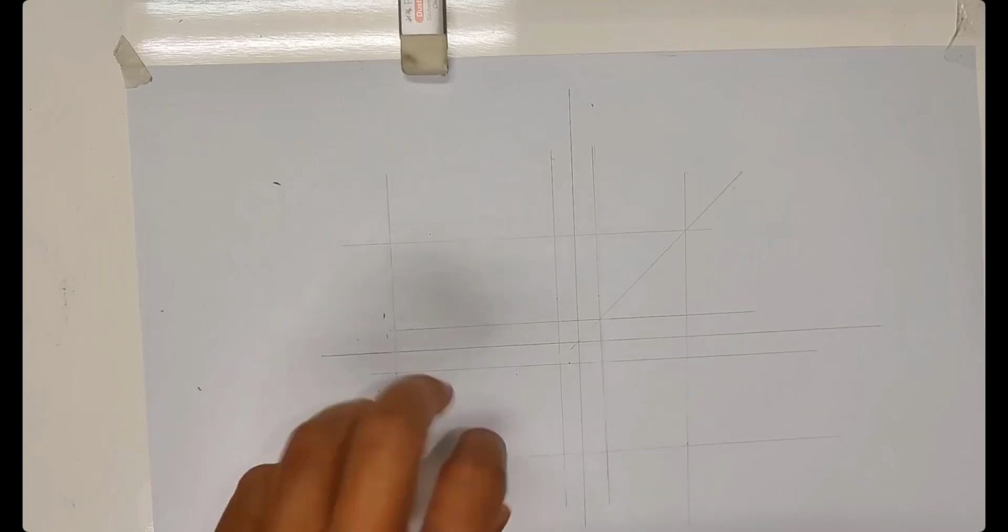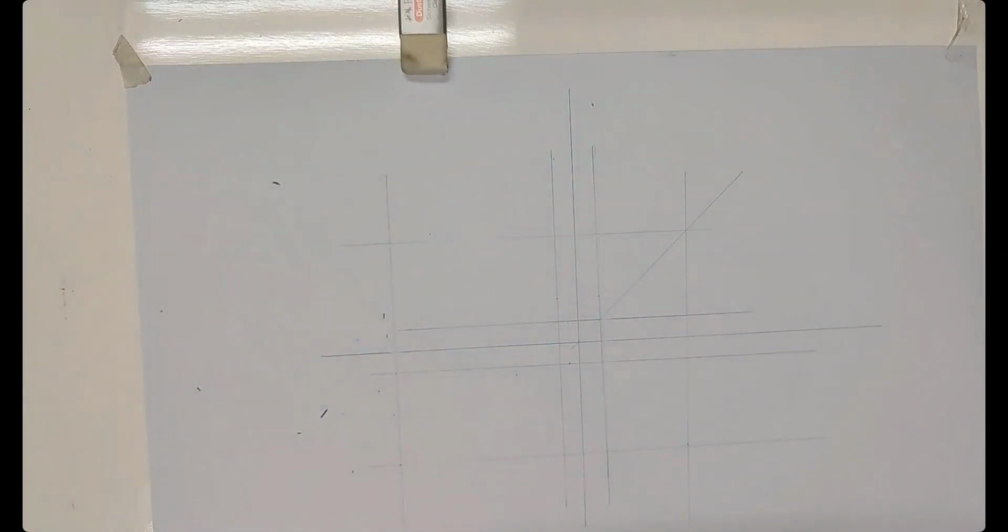Now if we have front, side view and top view, the next move is to decide which view clearly explains the base profile of the shape of this block. Do you understand what I mean? Which view? Front, side view, or top view? That shows the major cutting plane at 45 degree. Can you see this block has a 45 degree plane cutting, like a chamfer at 45 degree? Which view clearly shows that chamfer? Side. Yes, you are right, side view.